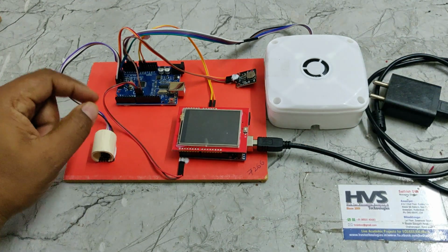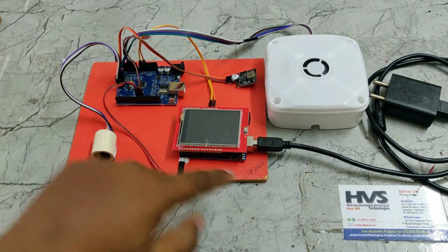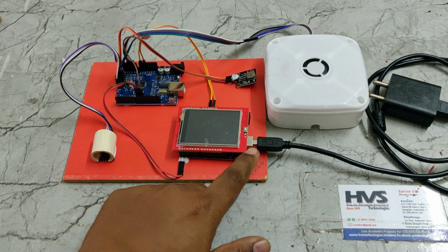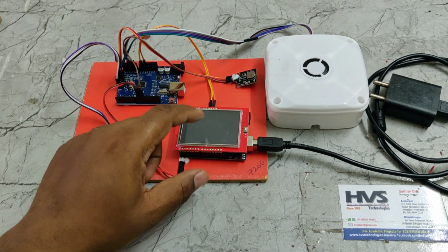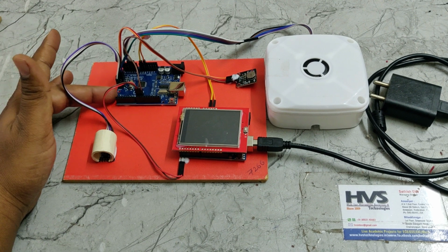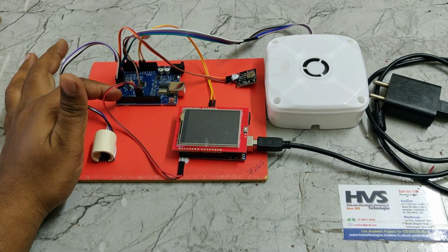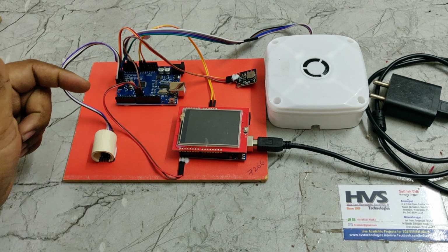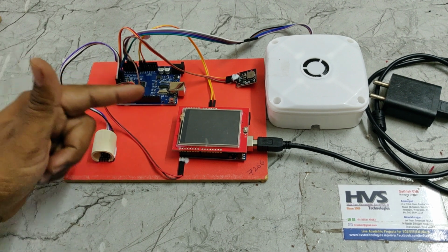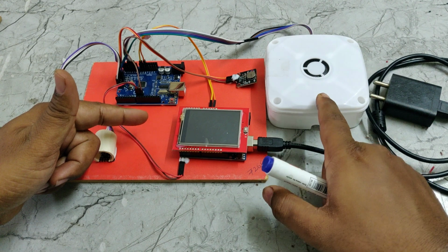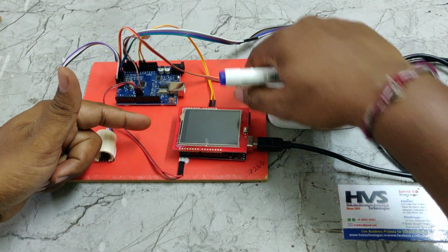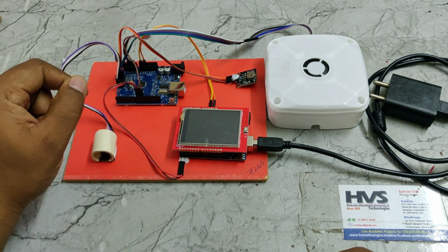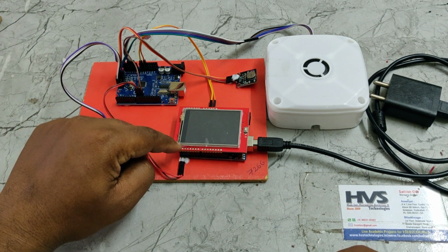Here we have interfaced two Arduino boards, an Arduino Nano board and an Arduino Uno board. One is for the TFT screen interfacing. It will get the data from the main Arduino, which is the master. The master takes care of reading input from the sensor module, and based on the glucose levels, it controls the outputs like the speaker as well as the vibration motor. The data is sent through serial communication to the slave Arduino Uno board,